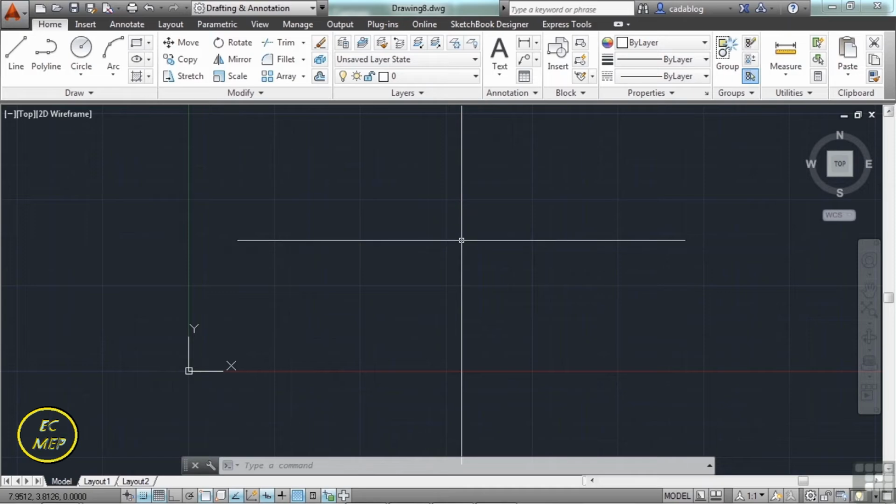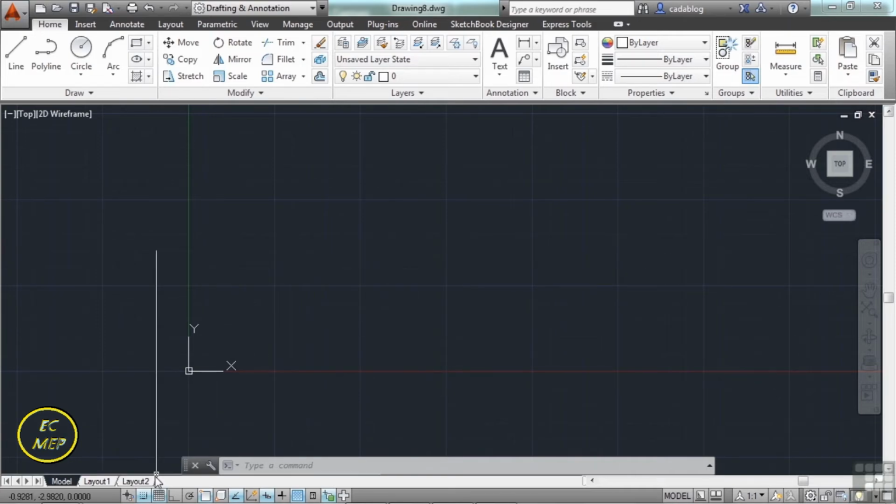When the snap feature is turned on, it's also a visual guide, not just an aid, but a guide, and it will tell you where you're going to snap to, as long as you set your grid to be the same increments or units as your snap. Now, to change the snap in the grid settings, you need to open up the Drafting Settings dialog box. You can do this by right-clicking on the O snap or grid icon in the status bar. Right-click and go to the settings.